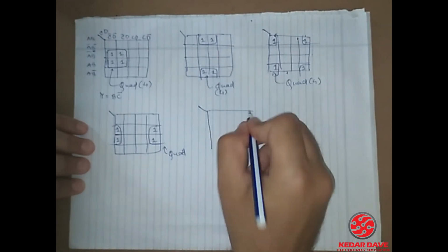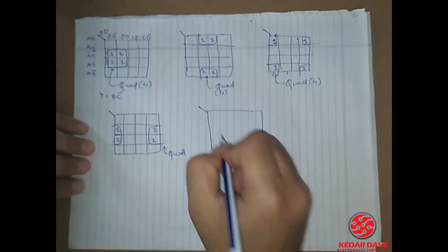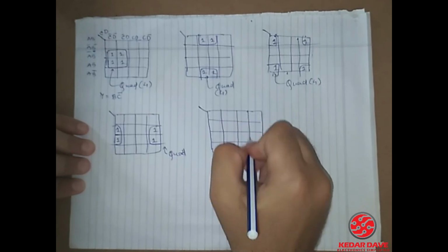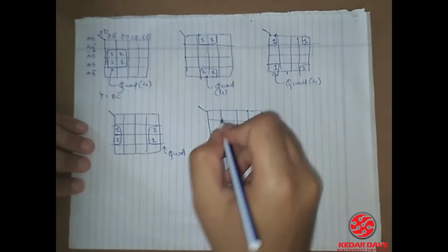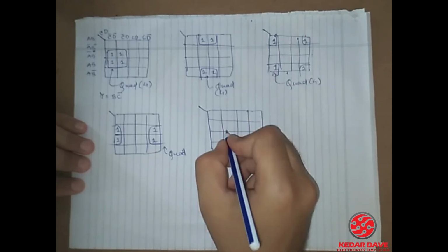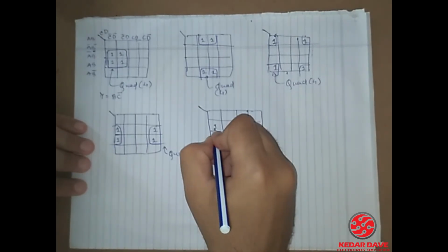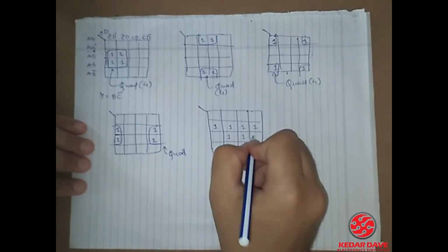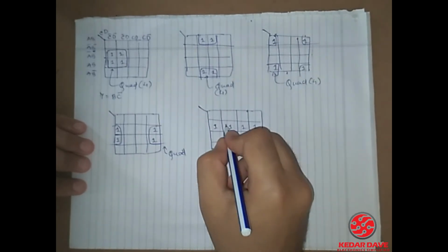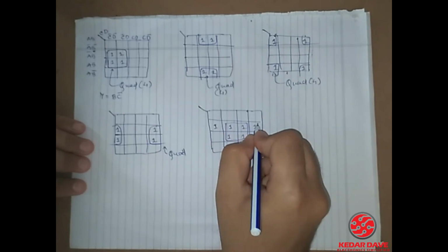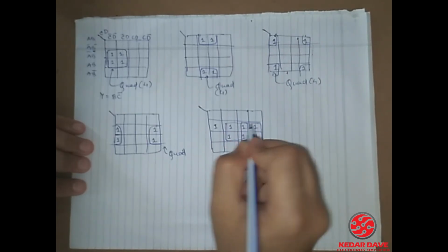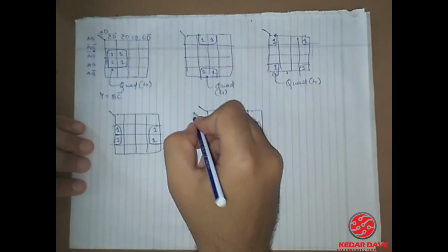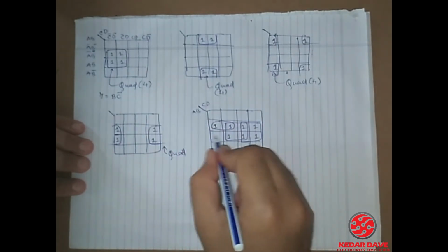One more case, that we can also overlap the groups, right? How can it be overlapped? So let's understand that thing. For the condition, we can make 6 pairs, or we can make 3 pairs in a single Karnaugh map. So this way there are 4 quads, you can say. This one is one quad, the second quad is being formed over here. So this is one quad, and this pair is being paired over here. So for all the pairs we need to simplify the equation.